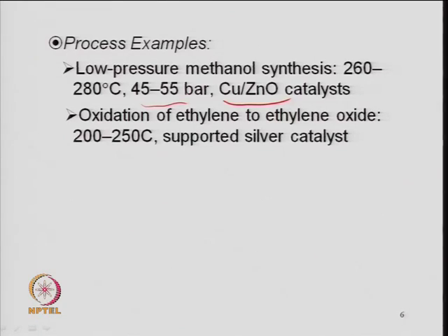So, it means you have saved a lot of energy, because high pressure reactors need more energy consumption, right. So, one can have a catalyst, then identify the optimum process for that catalyst, in terms of temperature, pressure, space time or residence time, and look at the hydrodynamics also, because the porosity, size, shape, strength of the catalyst will also affect the performance in the reactor.